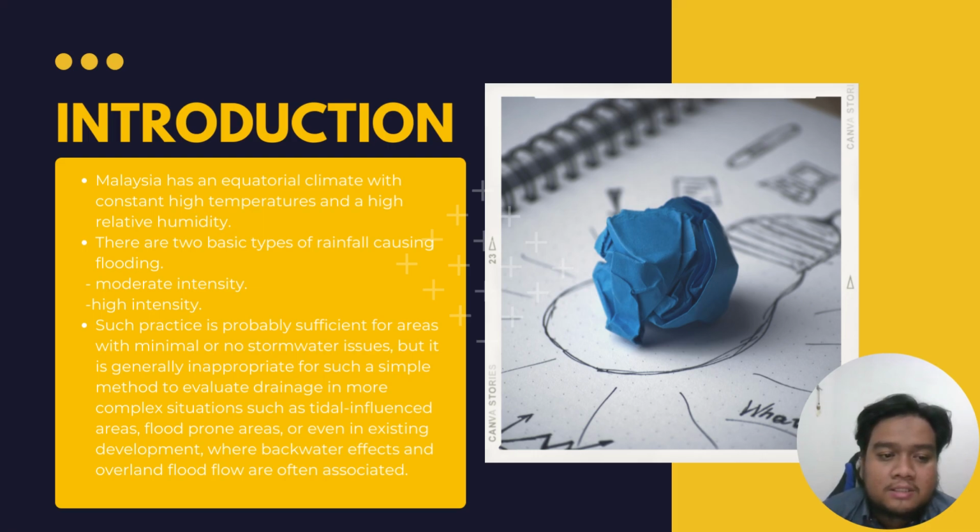This practice is probably sufficient for areas with minimal or no stormwater issues, but it is generally inappropriate as a simple method to evaluate drainage in more complex situations such as tidal influence areas, flood-prone areas, or even in existing development where backwater effect and overland flood flow are often associated.